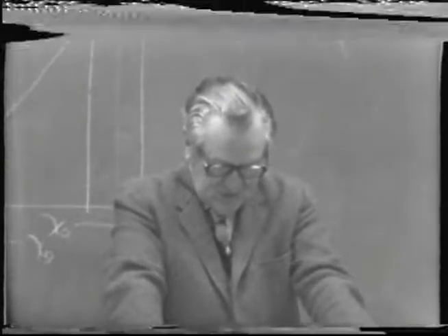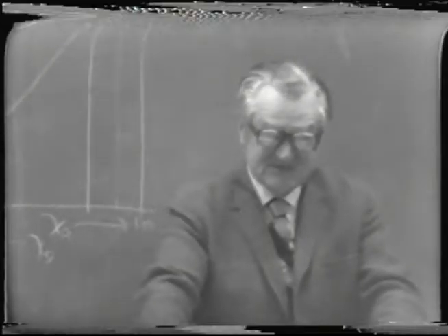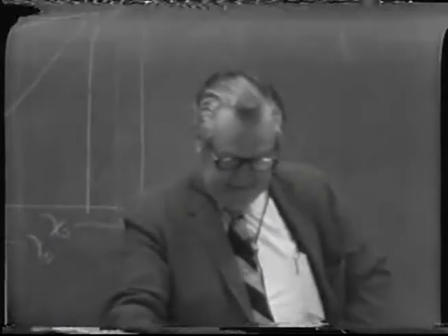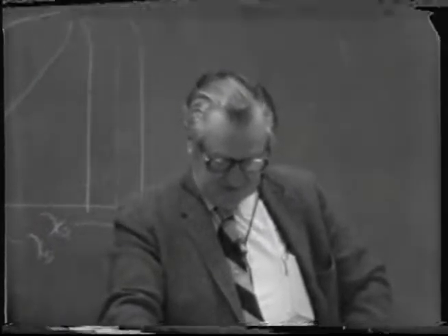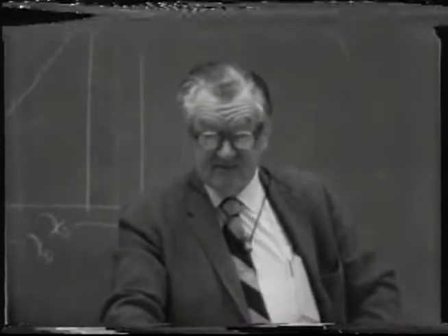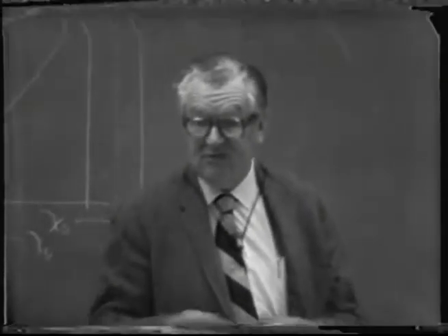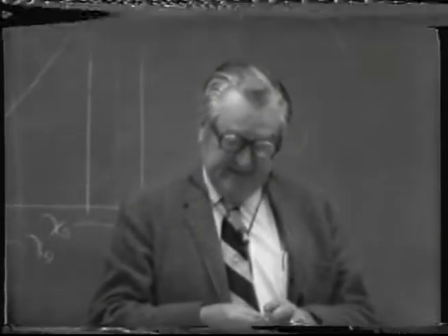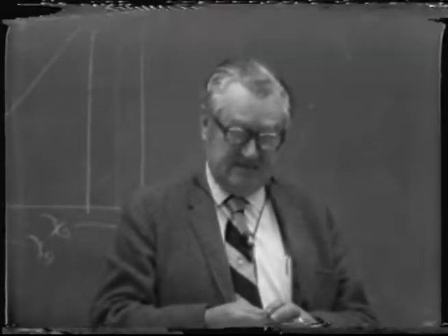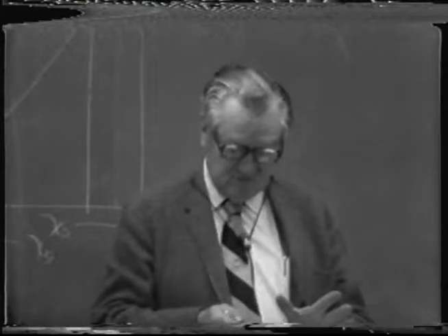We used to have much closer plate spacings, sometimes as little as 7 inches. And although they function, they don't function very efficiently, and they also operate at fairly low rates, considering the size of the column. And the tendency is to flood very easily. And so the operating rates are very limited when you have very close plate spacings.